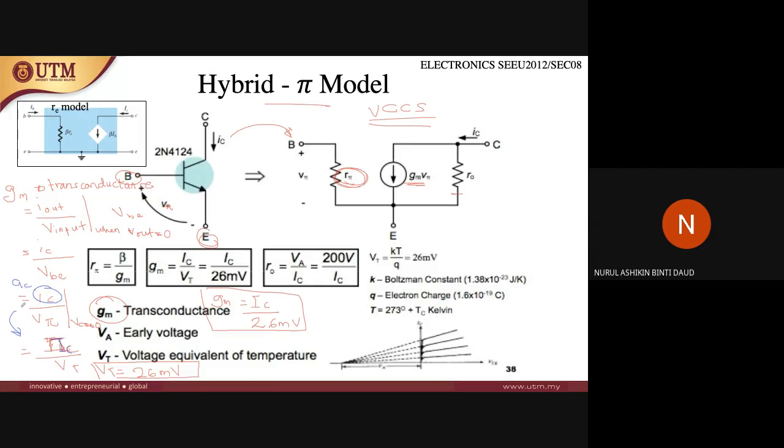Okay, so we also say that, sorry, not also say. Lowercase ic here represents when the source of the voltage is an AC source. Capital IC here represents when the current is from a DC source. So in this case, since VCE is equal to 0, we can say that this AC source can be equivalent to a DC source.